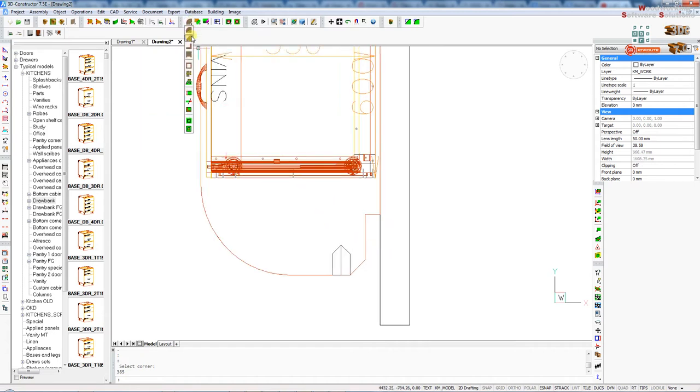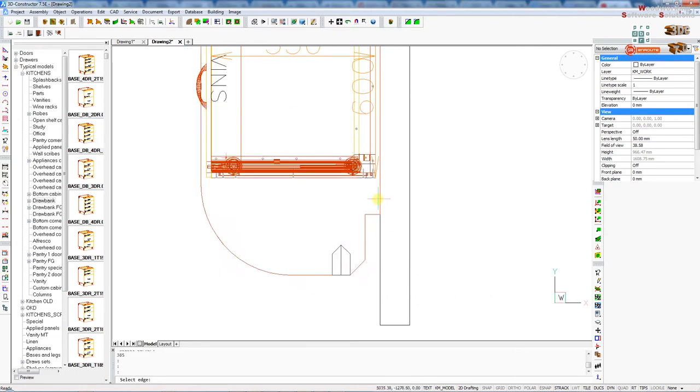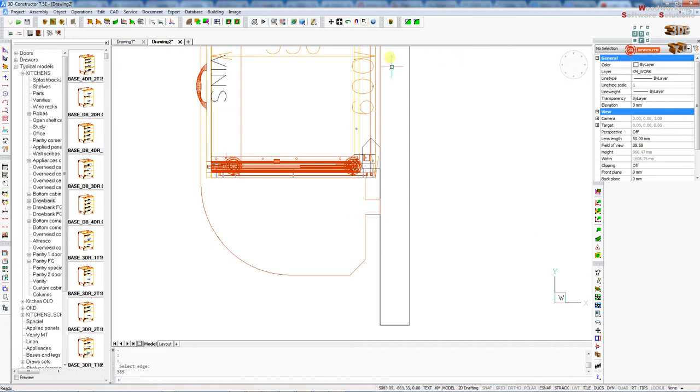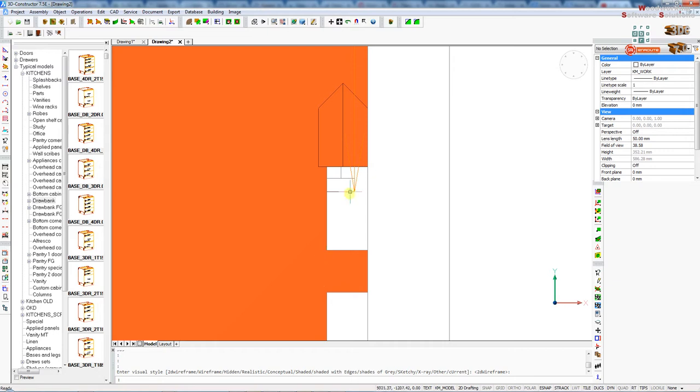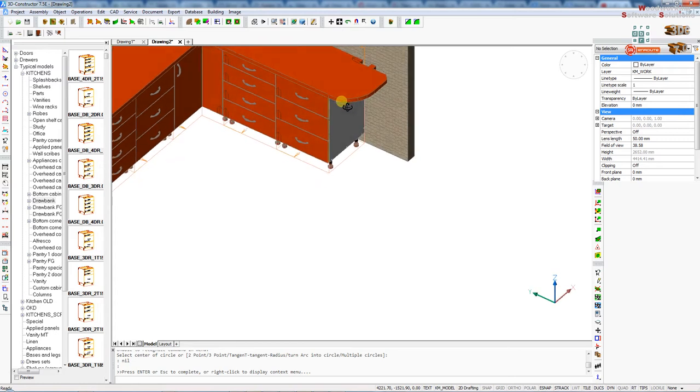The next operation is cut along the side. This operation also has a lot of different options, but we can go with a pretty standard one. This operation has a start point. Let's say we put the start point at 50, the length will be 100, and the width will be 50. You can see we've got this cutout here. Now our bench top looks like this.